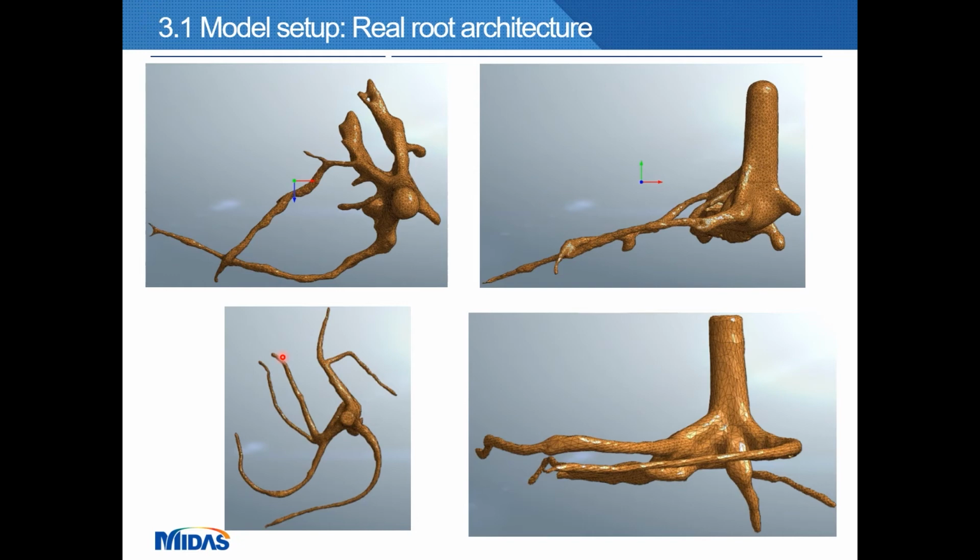However, as we decided, we try to remove the third order and higher in order to have reasonable results in MIDAS. This is not a limitation of MIDAS. The thing is that if we have more fine roots, when we try to reconstruct the mesh and the main roots, the software, CloudCompare and MeshLab, recognizes the fine roots as structural members. So in some cases, it identifies thicker members that were not real. So we decided to remove the third order and secondary order fine roots. In this case, we are only seeing structural roots, meaning roots that provide the stability of the tree.